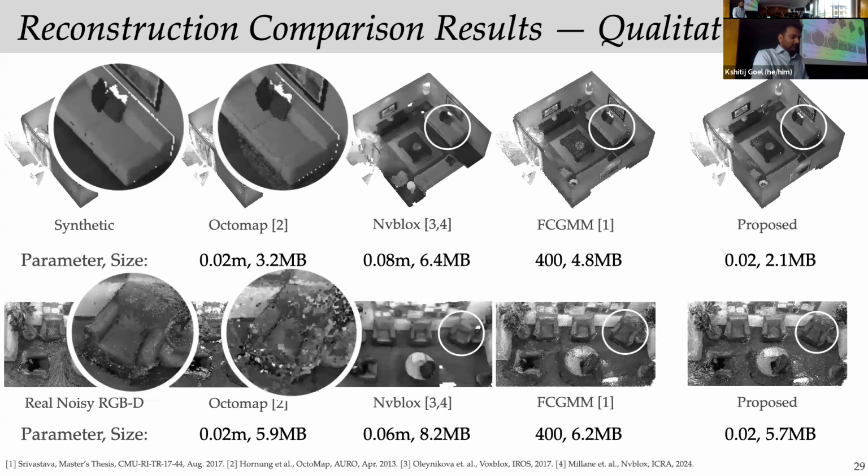For Octomap, we observe a good spatial reconstruction, but inaccuracies in intensity reconstruction. If you compare with the ground truth images, the intensity values are miscalculated in some of the voxels, such as the floor and the sofa in the top image. This is expected because the intensity values are not jointly modeled with spatial data in this case. These values are set by averaging nearby cells.